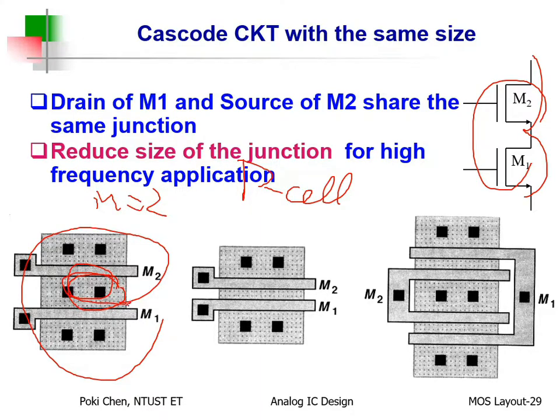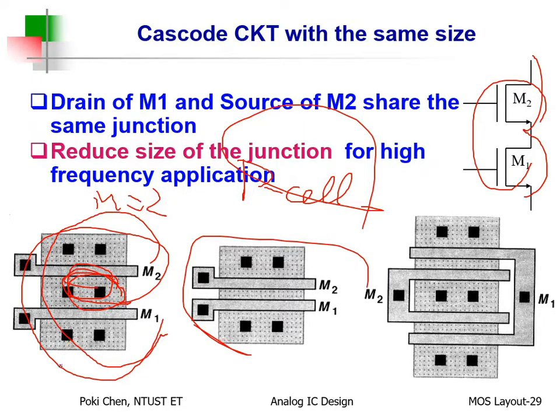If you remove it, because there is no connection at all, with a P cell you will automatically get something like this. But you can make it even better by yourself. Please flatten the layout. Then remove the portion you don't need, and make it even more compact than before.